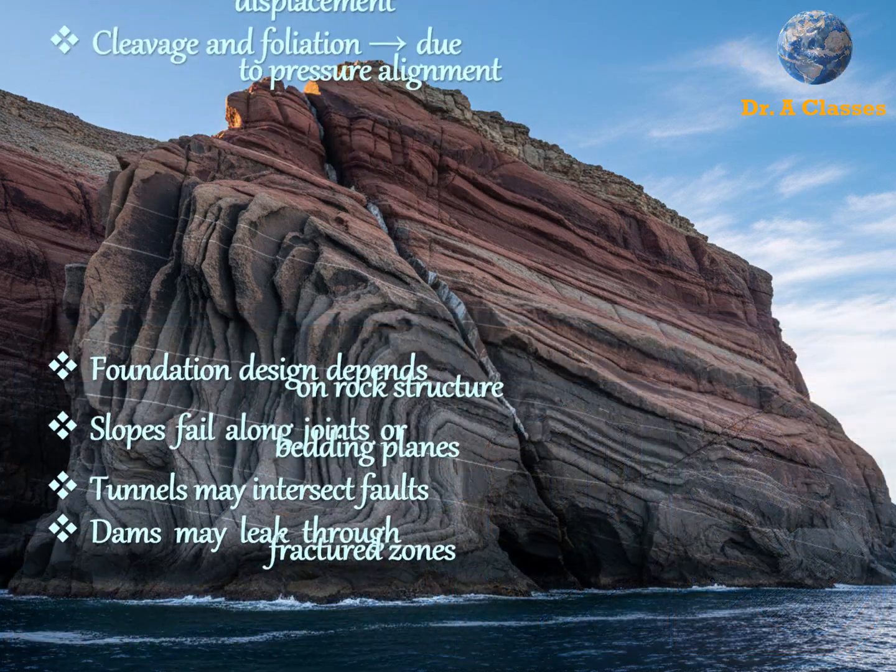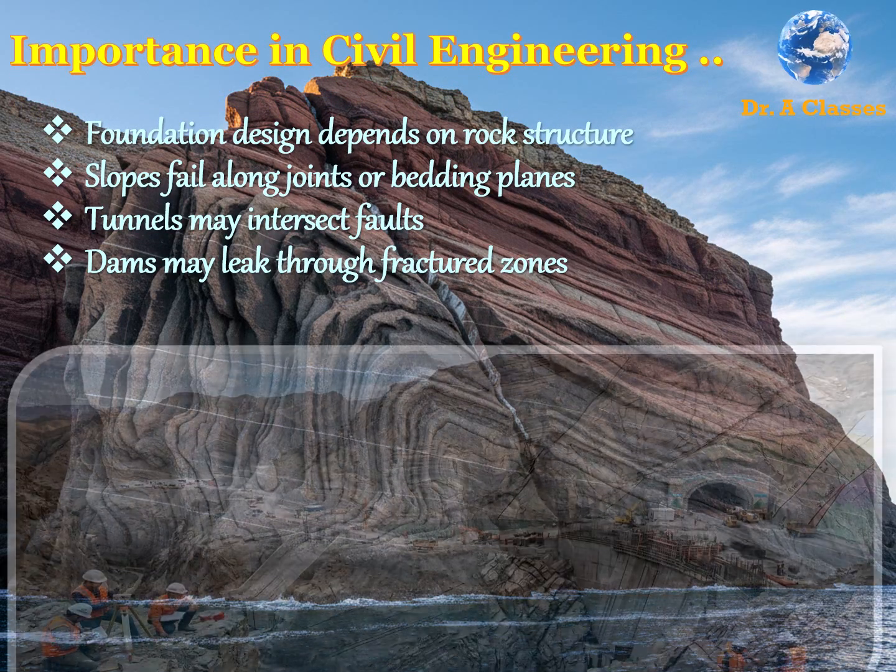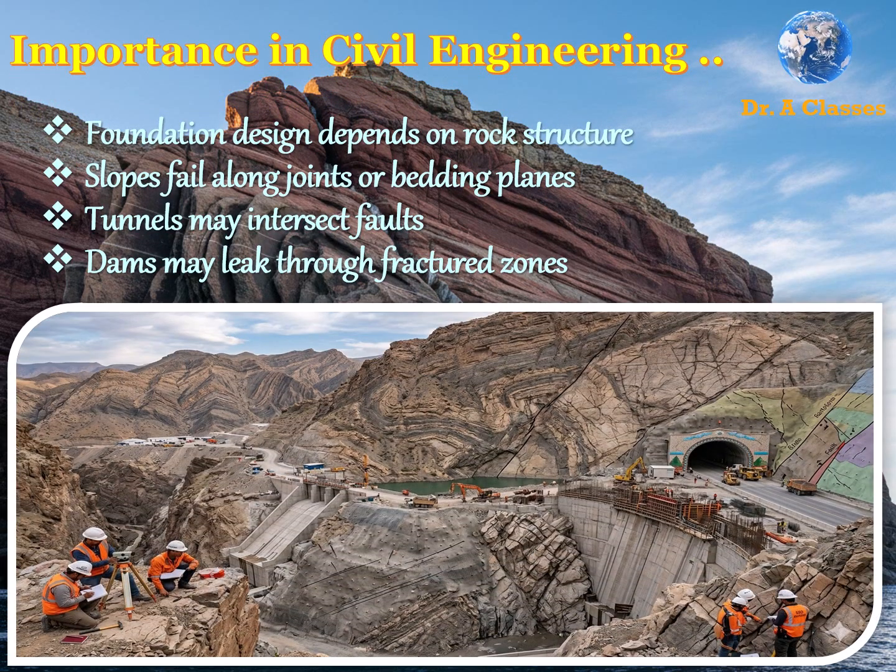Importance in civil engineering. For civil engineers, understanding deformation is critical. Foundations must consider bedding orientation, slopes may fail along weak planes, tunnels can collapse if they intersect faults, and dam safety depends on the presence of fractures. Structural geology directly affects engineering stability.